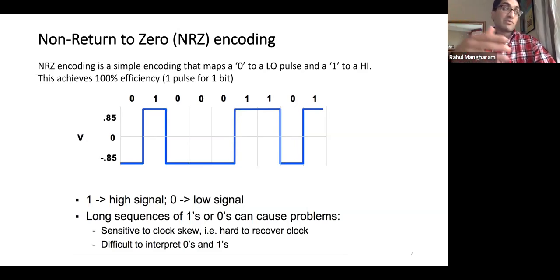And I'll maybe be going, because it's a little cooler over here, for example, or because of the manufacturing imperfections that are introduced, or because of the variability in the material of the crystal, I could be operating at 16 megahertz minus 20 or 30 hertz at some time, right? So that causes me and you to not have exactly the same synchronization, the same time step.